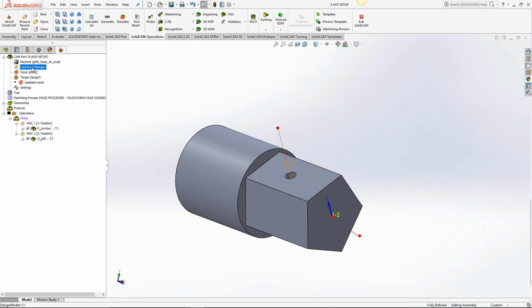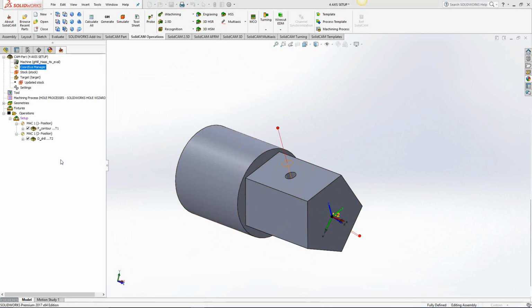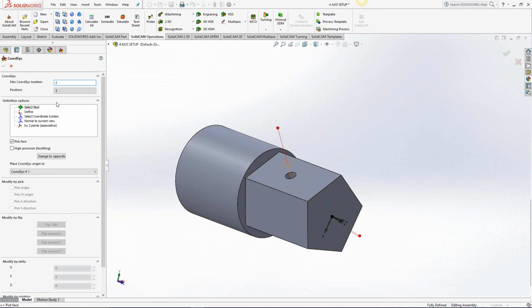But as an example of what you would do if you're working on a fourth axis part where you know the rotary axis, but you don't actually have a nicely cylindrical part like this, let's just go to Add. We'll set up a Mach 2 position 1. So basically this will be a second offset. If I don't have a revolved face, let's just say I had a pentagon kind of shape there, no revolution face, we can go to top center of model box.